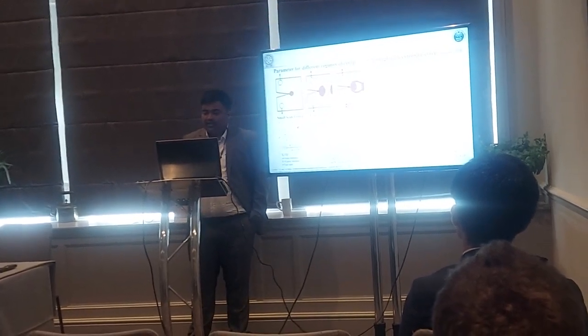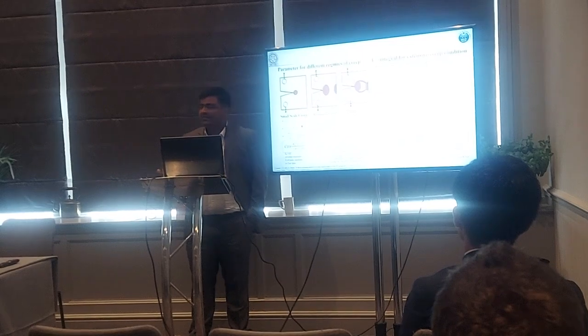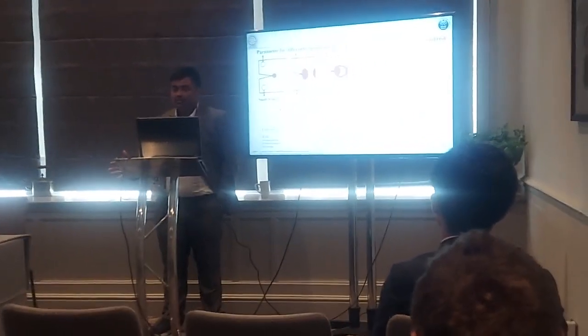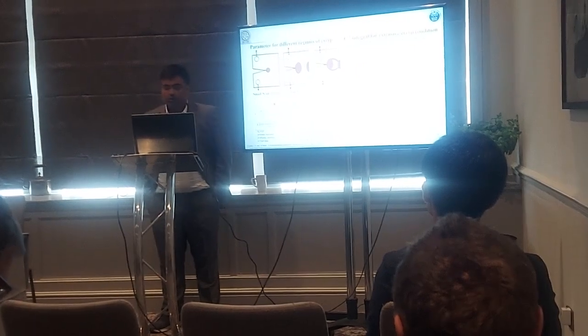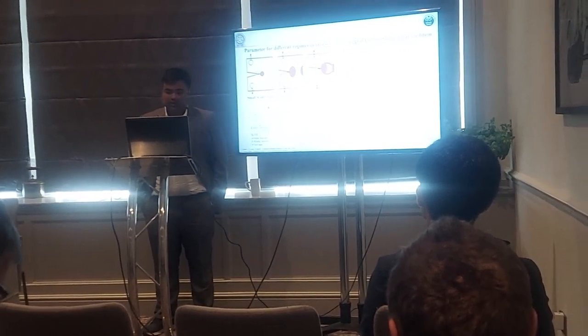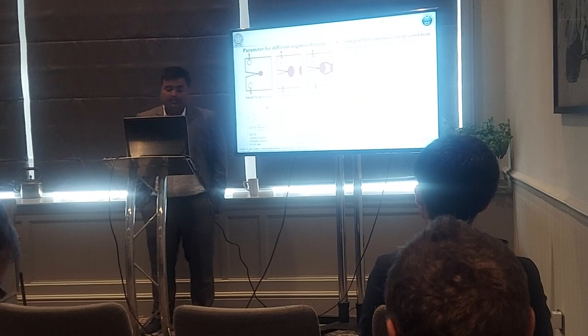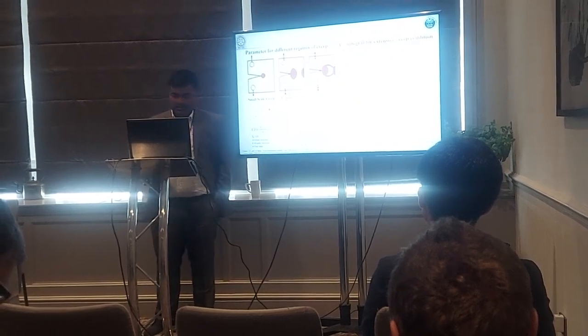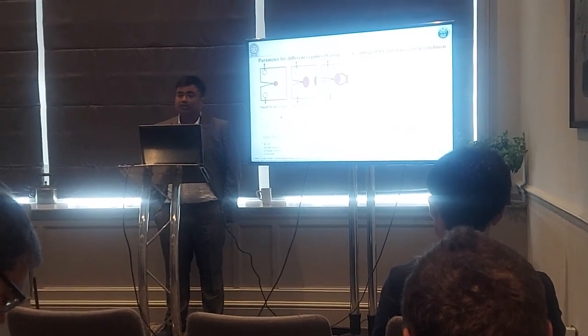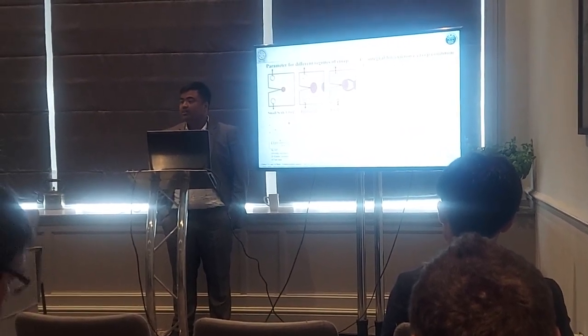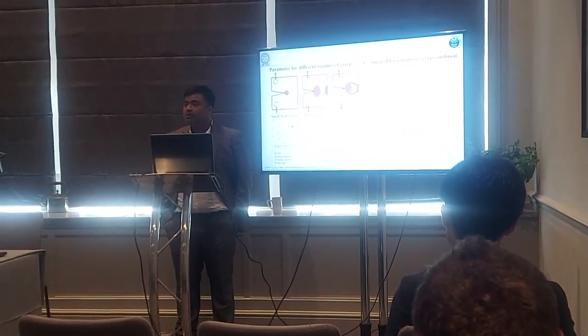Here is one thing. What is C star, how did it come into the picture, and what is the analogy with the J integral? I hope most of you are aware of the J integral. It was given by J Rice by considering the concept of deformation theory of plasticity, where only loading is allowed, no unloading.